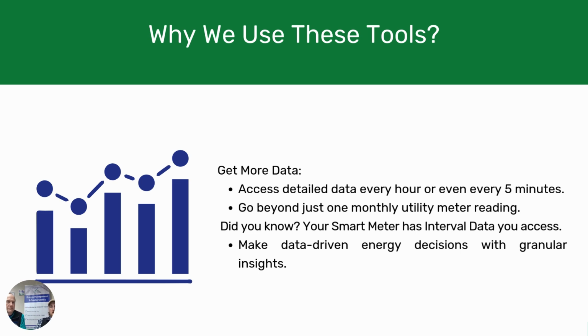So, as we get more and more data, some tools, like that thermal camera, will give us an instantaneous point. What's our reference to a given point, and it'll tell us what that temperature difference is, so we can make a calculation of what the building insulation and the building envelope is doing. But some of those data loggers, like the one we just looked at a few minutes ago, track temperatures and humidities and lighting and occupancy.